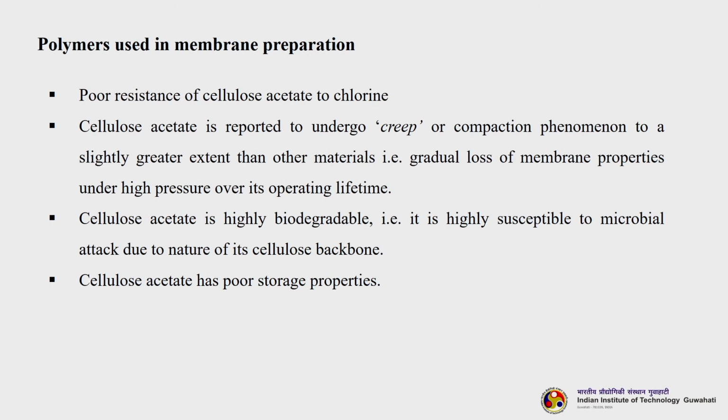Cellulose acetate is highly biodegradable. This is another big problem if you are using this type of membrane for some bioremediation or wastewater treatment process, or for the production of some biopharmaceutical drugs. It is highly susceptible to microbial attack due to the nature of its cellulose backbone. So, microbes will actually try to eat the cellulose as a source of glucose for them. So, cellulose acetate has poor storage properties.